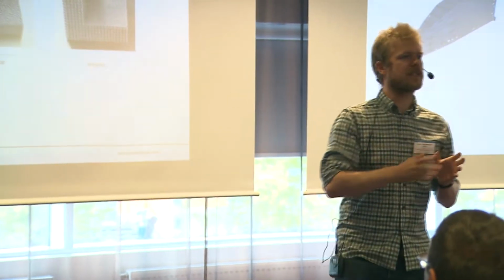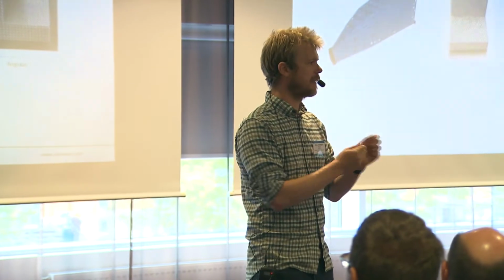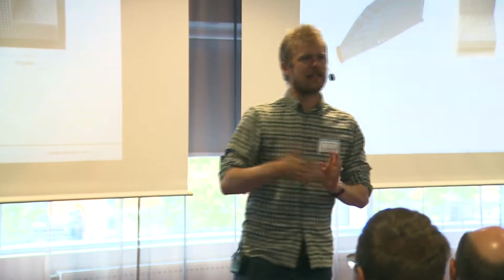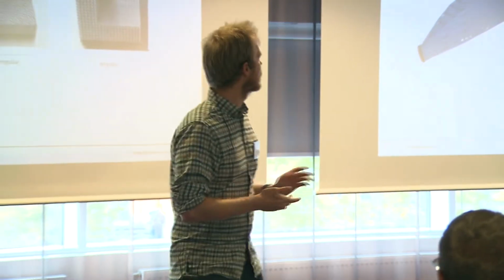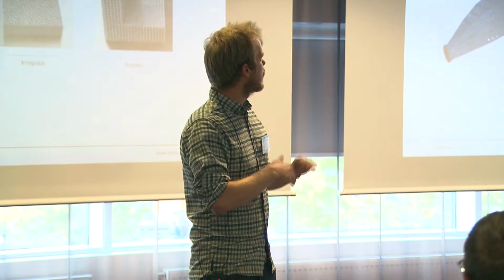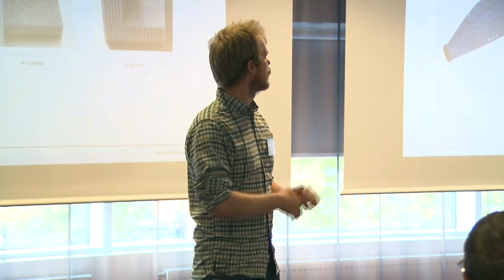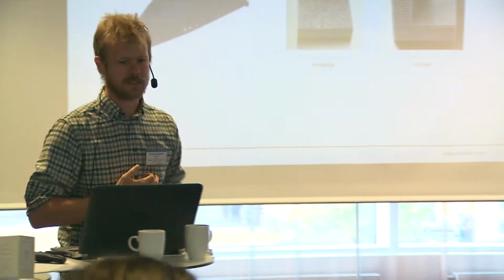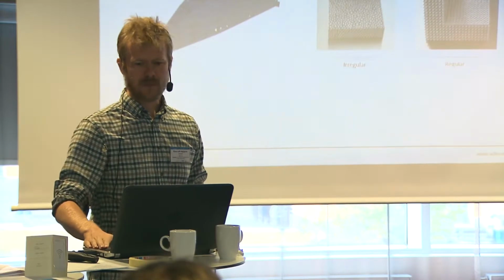With the regular lattice structure, you can design your unit cell, and then you can do a BCC type of lattice or an FCC type of lattice and put it in there. And there are plenty of studies on metal printed lattice structures and compression testing them and finding good material properties, etc.